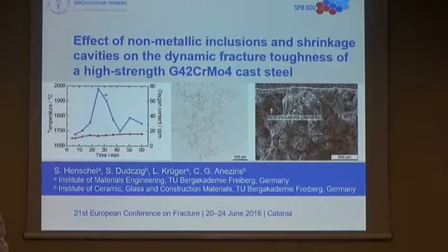These are standard notched and pre-cracked specimens, which are also equipped with a strain gauge near the crack tip, which was statically calibrated to measure the force, and also a force measurement in the top of the Charpy impact testing machine was applied. And this strain gauge was also applied to measure the critical point of the test, and at this point of instability the J integral was calculated.